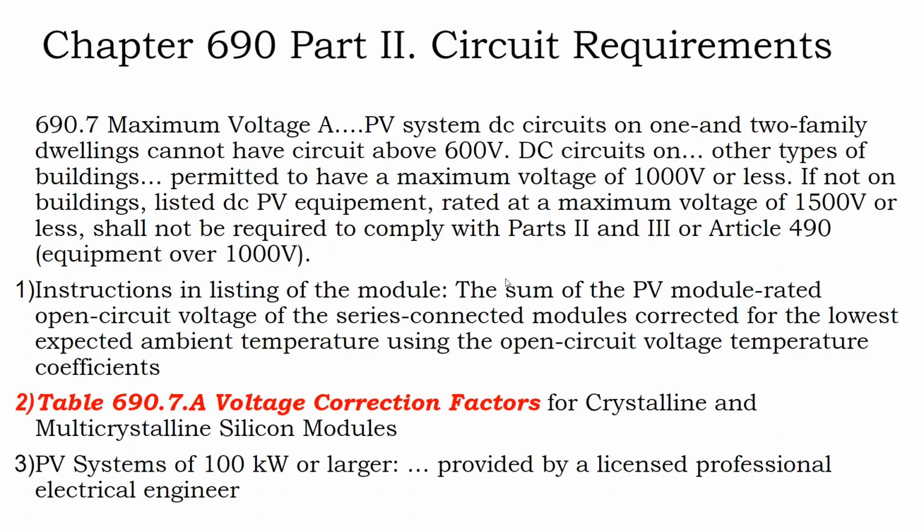If I'm doing a ground mount that is very far away from the home, the voltage drop from point A to point B becomes significant. And the cabling cost for the amperage from point A to point B becomes significant. And the way you decrease that cost is to do exactly what the electric grid does, which is increase the voltage and drop the amperage.